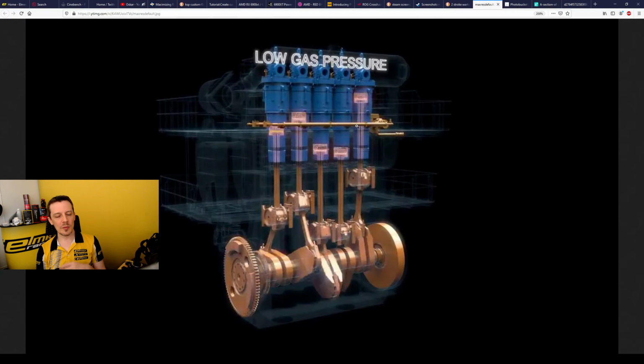So yeah, some two-stroke engines also. Typically these will be in extremely large energy production, or really big ship engines. You run a two-stroke engine with the inlet port at the bottom of the cylinder, so you can see the piston is below this inlet port. At the top there's no piston to open the exhaust port, so you run a poppet valve for the exhaust system, and this is actually really beneficial, because then you